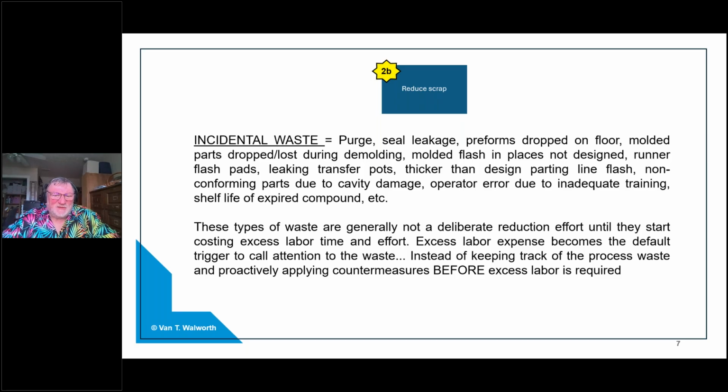And that's an easy way for excess waste to have been taking place, so that you can reduce some of the waste just by minimizing the purge and eliminating purge on presses and parts that don't need it, because there's a lot of parts that don't need that. The injection world of presses is full of a lot of parts, like for instance on horizontal presses, that run on automatic. They're not purging rubber. They're running on automatic. And so purging is important to a lot of parts, but not every part, and they should be considered accordingly.